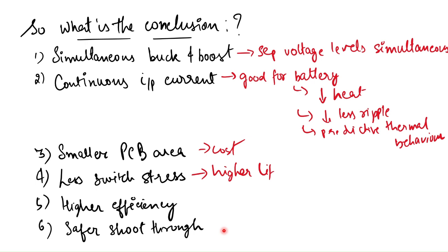I would like to add, batteries don't fail because of the voltage. They fail because of how the current is drawn from them. Now, conventional buck and boost converters pull current in sharp pulses, creating heat, stress and causing long-term damage to the battery. This is where the IDOC converter changes that by sharing energy between buck and boost outputs and maintaining continuous inductor conduction. It draws smooth, steady current from the source.